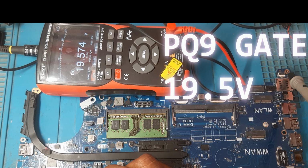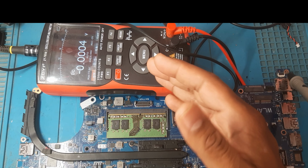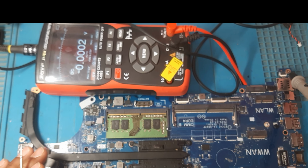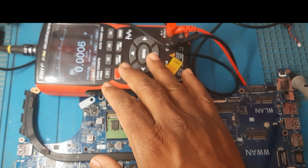See, the gate is also 19.5, which means the voltage divider is not happening. Why is it not happening? Many technicians won't check that logic. Directly they will short this MOSFET, from source to drain, and they will get the voltages. But actually it's a wrong method.